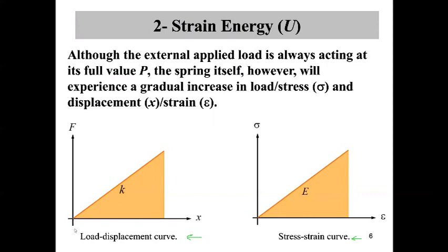The lower left figure shows the load displacement curve for linearly elastic material. Notice that the slope of the load displacement curve is K. The lower right figure shows the stress strain curve for linearly elastic material. Notice that the slope of the stress strain curve is E, where E is the modulus of elasticity of the material.